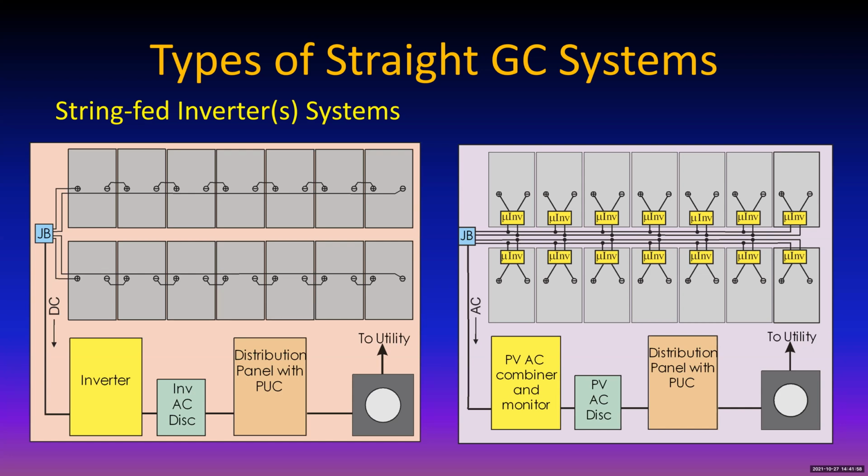The wiring, they're all snap connectors. You snap wire the modules together. You could have gone out binging the night before and not mess up on how you wire the modules together. You might fall off the roof, but that's another story. So in any case, they're male and female connectors or plus and minus connectors on each of the modules, so that you can only connect a plus to a minus, not a plus to a plus.